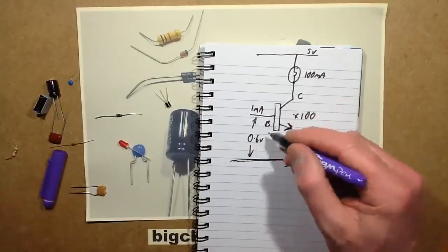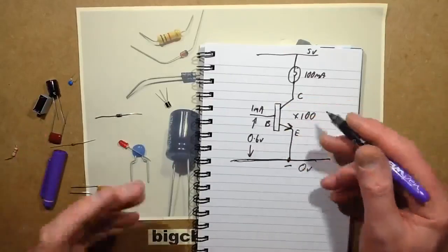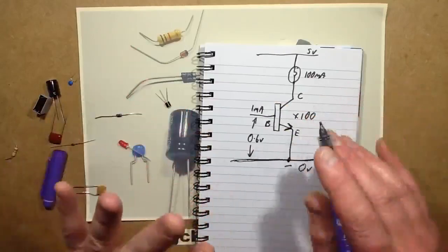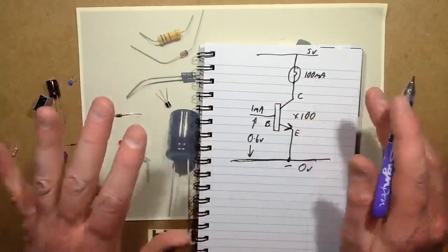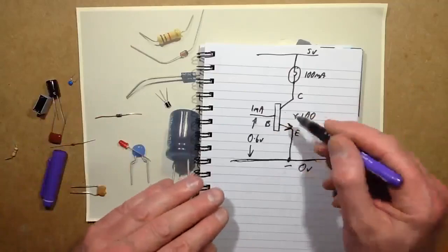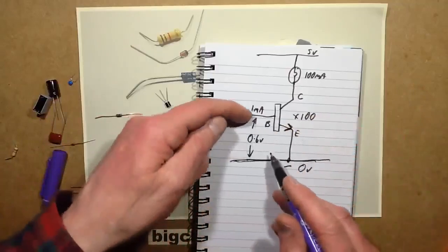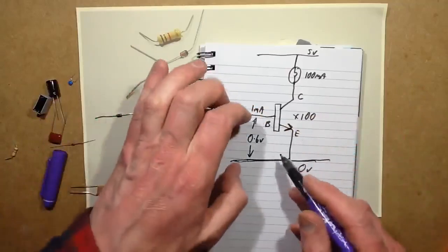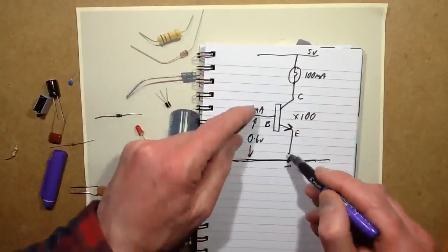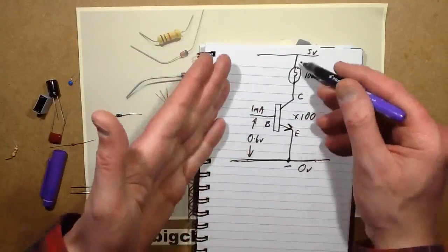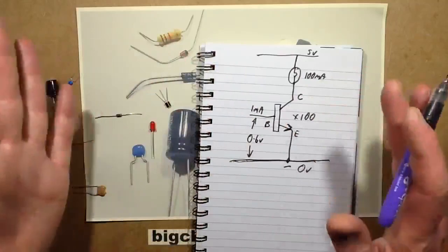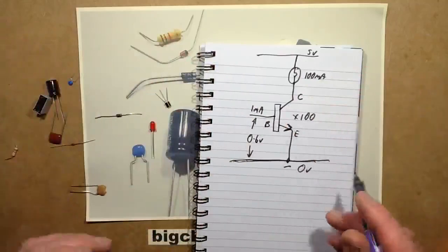You can also use them in other formats, like for voltage and current regulation, things like that. But just knowing the basic operation, that as soon as the base has X amount of current going in at roughly about 0.6 volts above the emitter here, then the collector current will flow. That's all you really need to know just to get started.